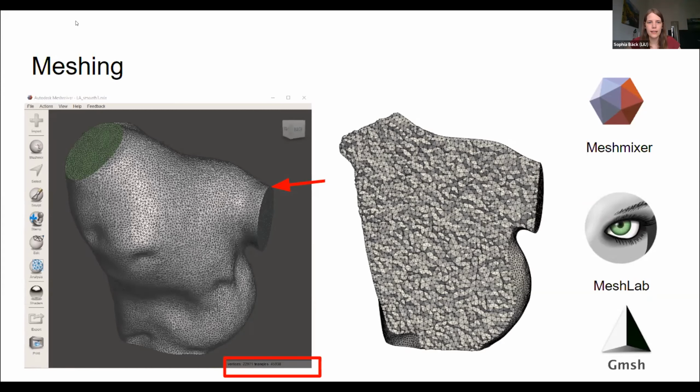Since we were using the ANSYS student version for our CFD simulations, we were limited in the number of elements. Therefore, we couldn't do a so-called convergence analysis, where you would create several meshes with a different amount of elements to find what resolution you need to get accurate results. So we just used the maximum amount of elements possible. And now I will go on to explain the Fluent simulation.